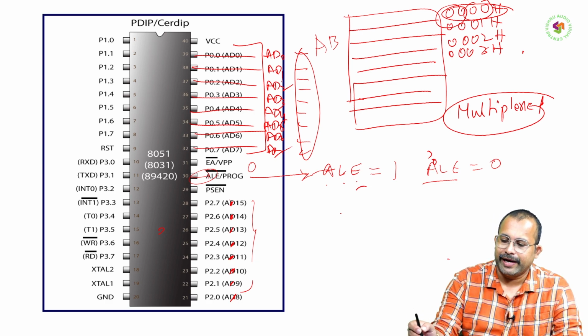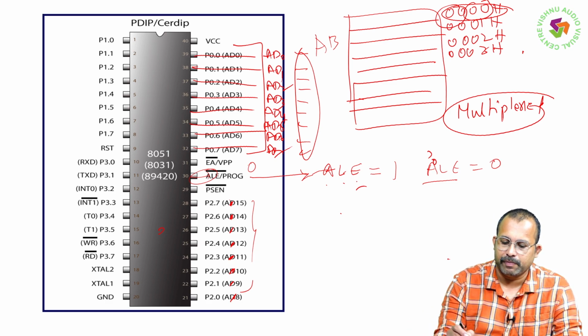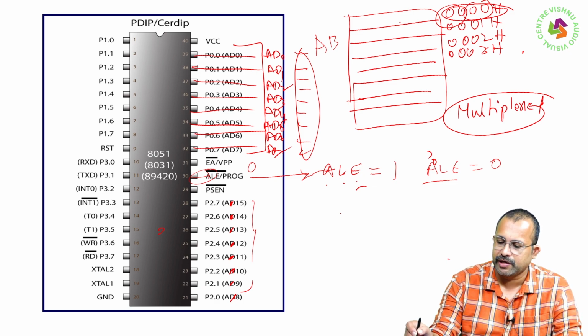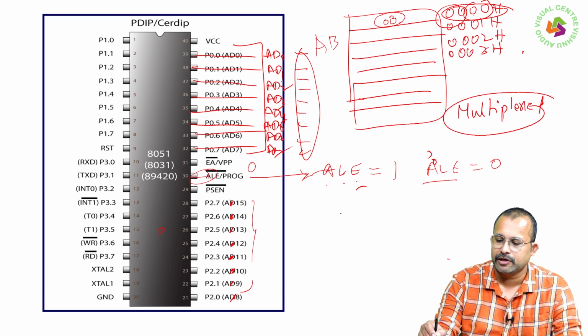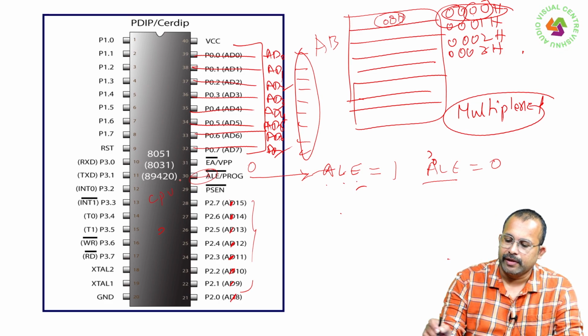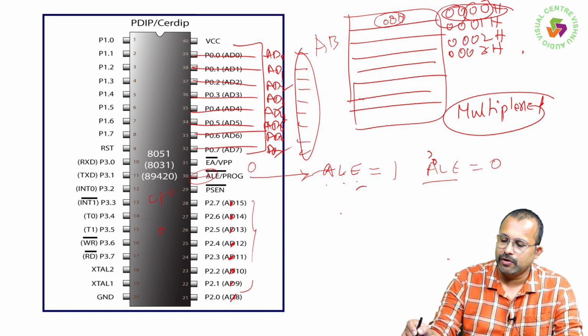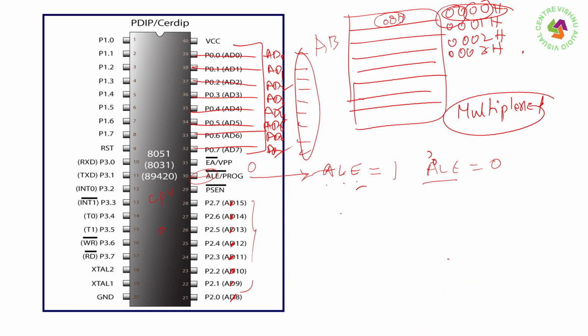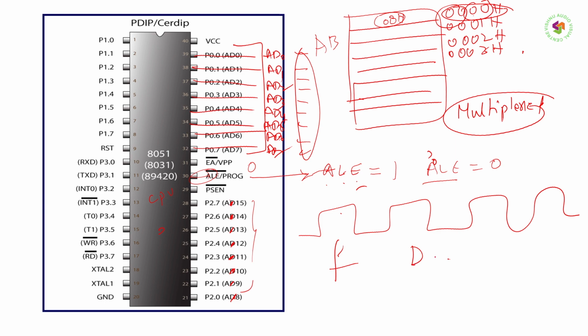So when data is being read, here this is a memory location and its address. If an 8-bit data 08H is present over here, and the CPU of 8051 is trying to read the memory location 0000H, where 08 is present, during the first clock cycle fetch will happen, next decode will happen, and execute will happen.